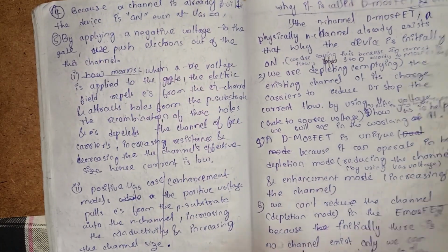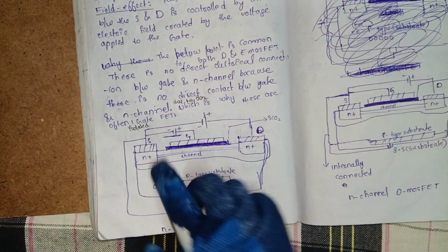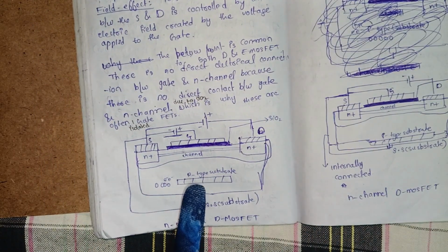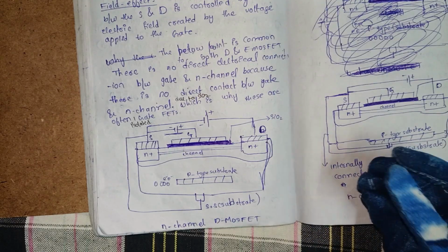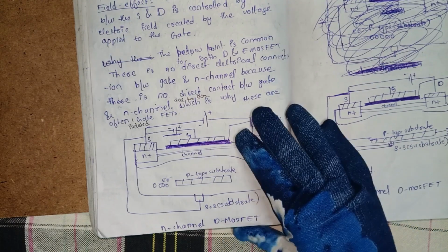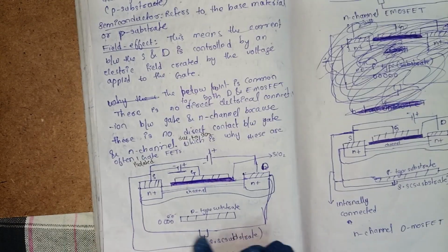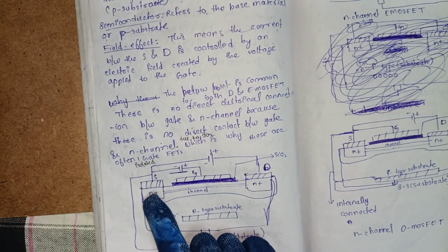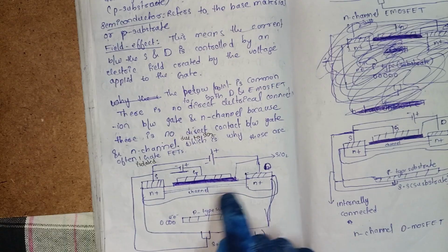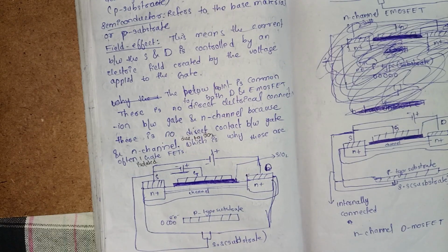In the circuit, we have to observe that source and p substrate are short circuited to maintain the p-n junctions reverse biased. This is one p-n junction.